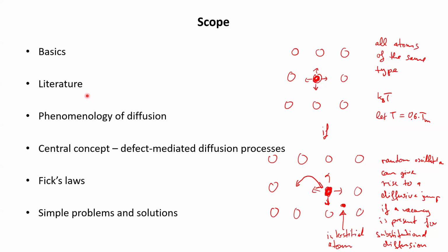They're coming from the microstructure, right? Because you have a very complex microstructure. You have maybe several phases, or at least you have grain interiors and grain boundaries. And you have dislocations, and you have vacancy clusters. All of this affects diffusion.